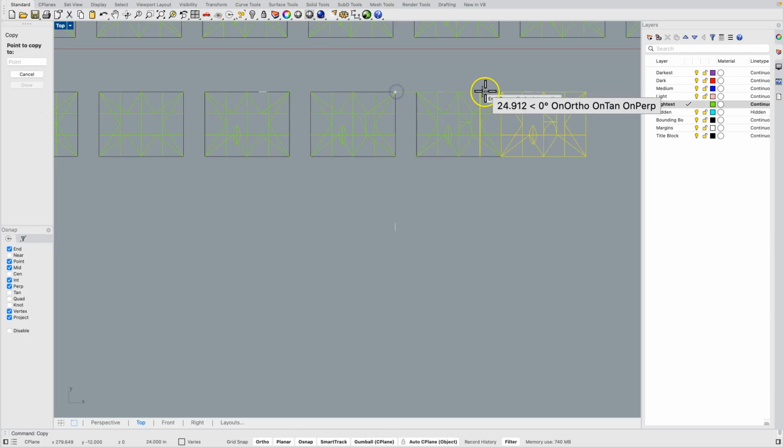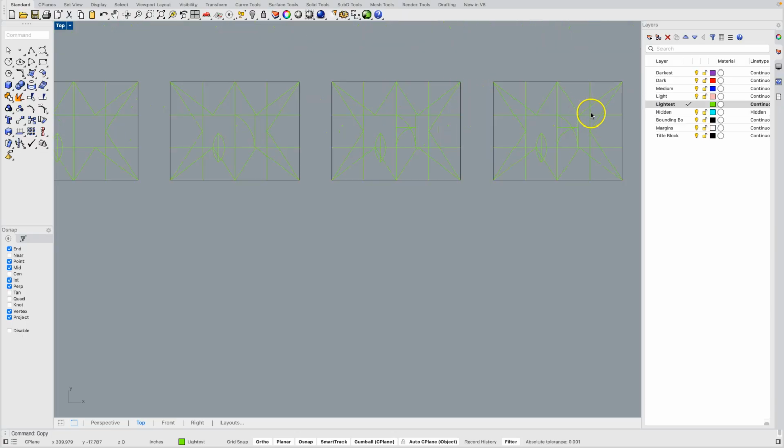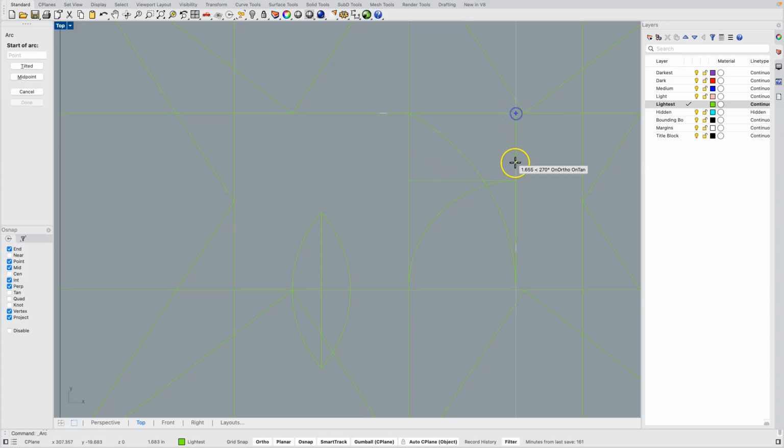Copy again. This time I'll play with arcs now that we understand them. Center, radius, snaps over. And you'll notice that I'm snapping because I have ortho on. Ortho is overridden by any object snap, but ortho means orthographic. It goes up and down, left and right as a snap. And again, these are things that come up in previous tutorials about how to use these various tools, okay?